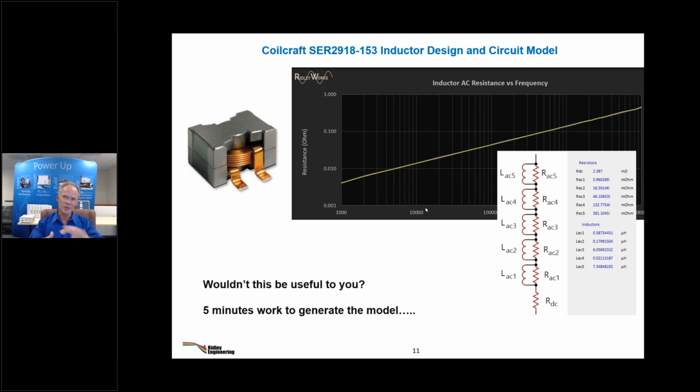So the proximity loss, which is excited by those field strengths between the layers, is cut in half, and then that means the proximity loss is cut down by I squared. So it's cut down a factor of 4. That's why these AC resistances climb so rapidly, because you get current circulating and it's I squared R. So phase splitting the windings is always good.